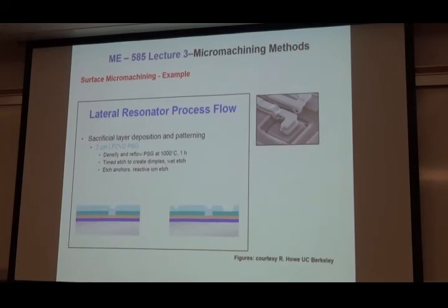So first let me answer why we put the N-plus layer. The first accelerometers, people were using them, and essentially what you're doing is pulsing these things billions of times, and it turns out over a period of time charges build up. And the charges are passing through the wafer and then going to the electronics.